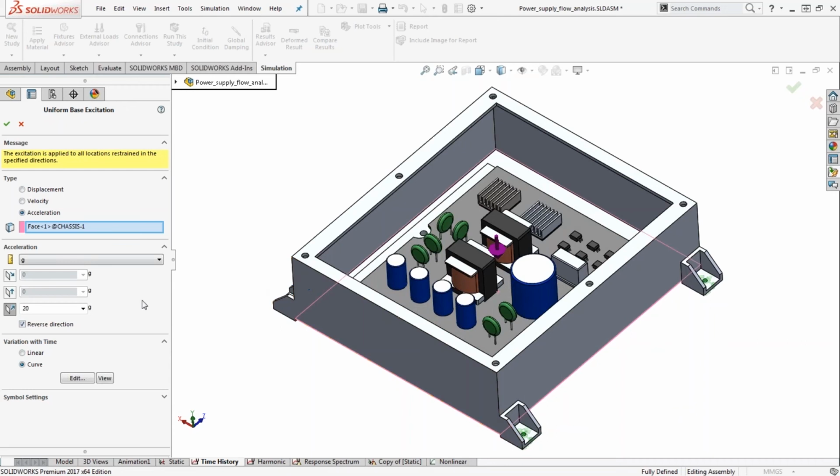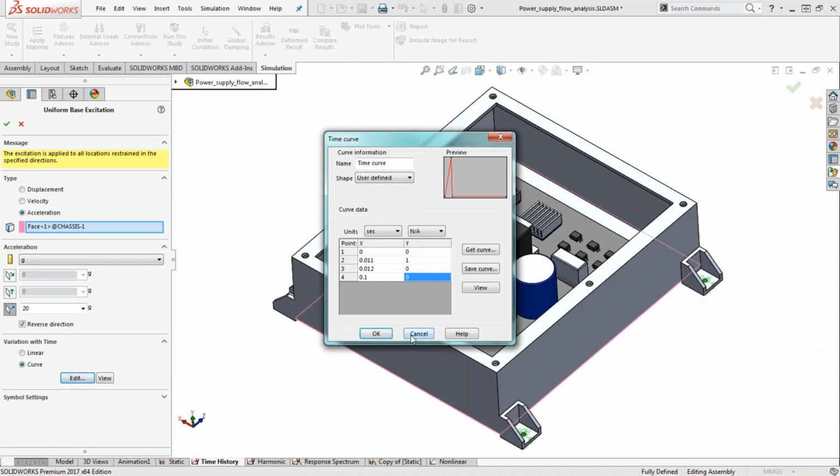split second there within the model, where maybe we're representing some sort of impact, where, again, we can get that data from some sort of mil-spec or whatever standard or whatever scenario you're running. Now the main input here that changes is that the loading is changing as a function of time, where the results are now back to stress and displacement, but we can see how those stresses and displacements are changing as a function of time, where we can then take a look at the response as well.